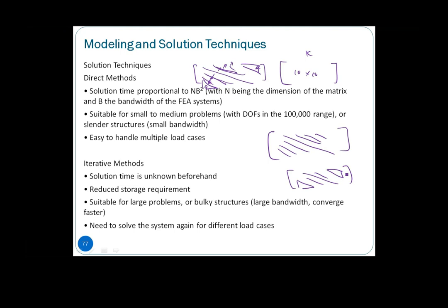In the case where I want to change loads, or add another load at another node, it's easier because we build K U equals to F. We can always change this F if I involve multiple loads. If I have other nodes, the load can also be easily added, and then you solve the whole thing again. Okay.